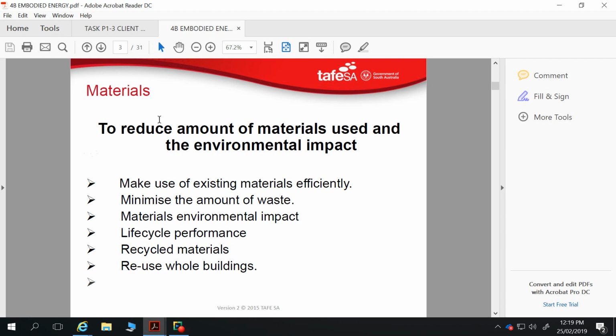So a lot of our materials come in those specific dimensions. We could say, I want 2780 high ceilings, and then your plasterboarders are going to have to get two 1200 sheets and cut off 370 mil of a sheet, and then cut off 370 mil on the other side, because they want neat formed recessed edges and don't want a cut edge exposed partway through a wall. So you end up with a 600 or 700 mil slab of plasterboard that goes to the skip.